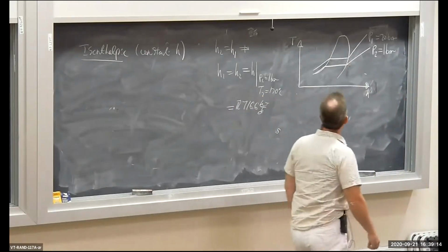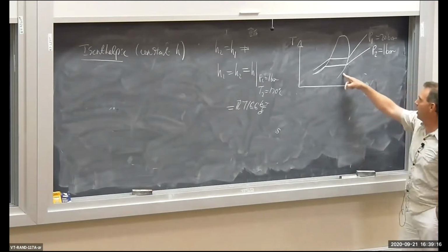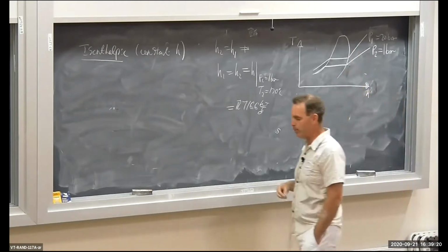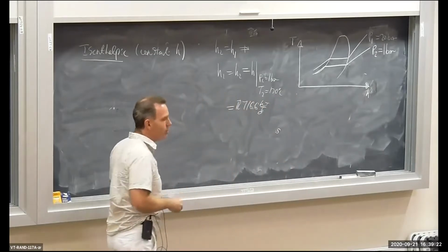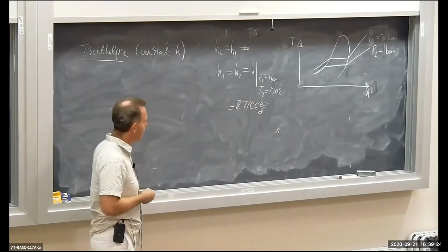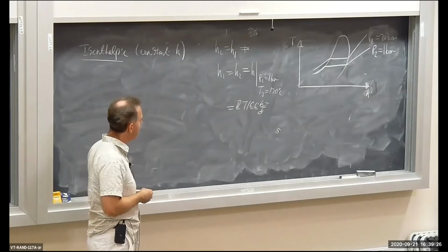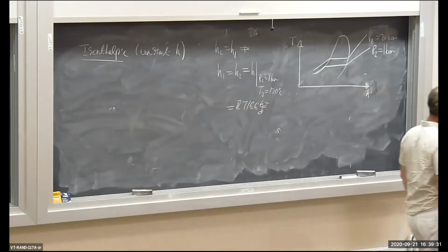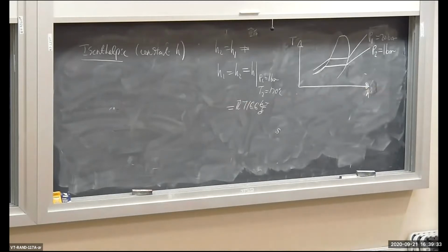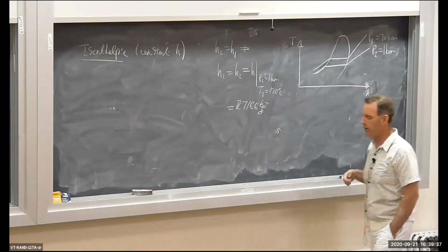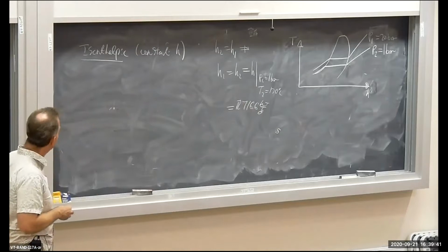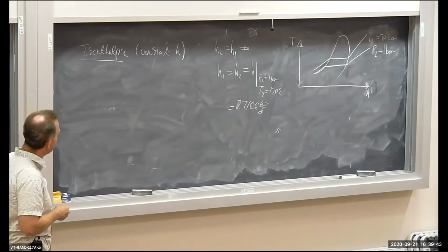Remember, the saturated vapor side of the saturation dome curves in this kind of strange manner compared to the TV and the TU plot. That's just what enthalpy does. So, strictly speaking, TH and TV aren't exactly qualitatively the same. You get this odd behavior on the superheated vapor side. Okay, so let's calculate the quality at state one.